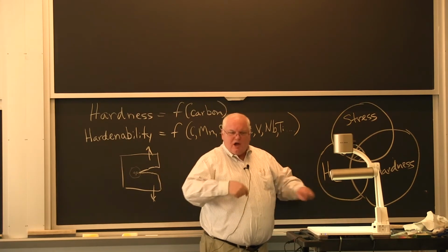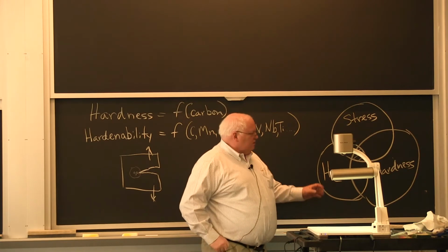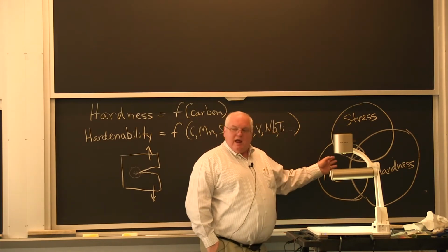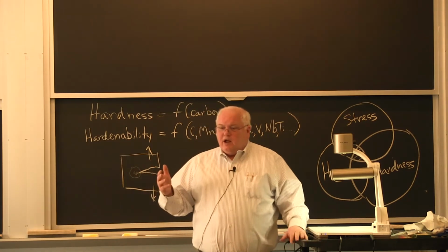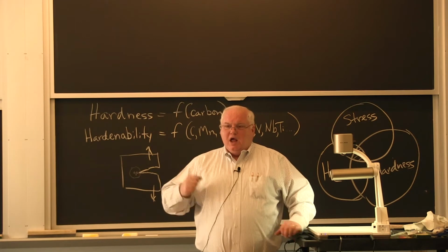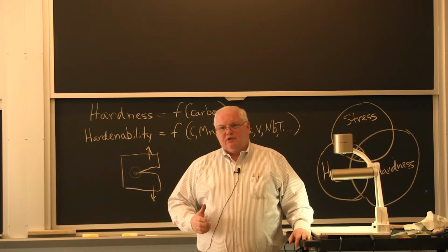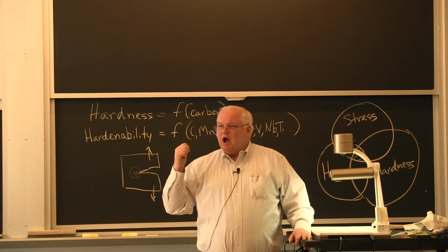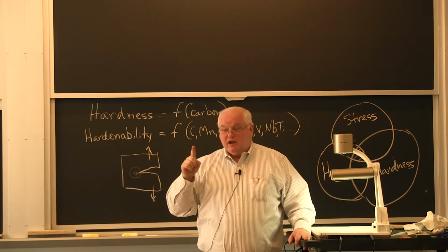There's some little clerk there counting your stubs before you can get more electrodes. They didn't have all these hydrogen controls, and so some guy welding at night would hear this piece that had been welded during the day, and it'd be a big boom like a rifle shot. Okay, a hydrogen crack just ran through the part they had made that day, 8 hours earlier. Delayed cracking.